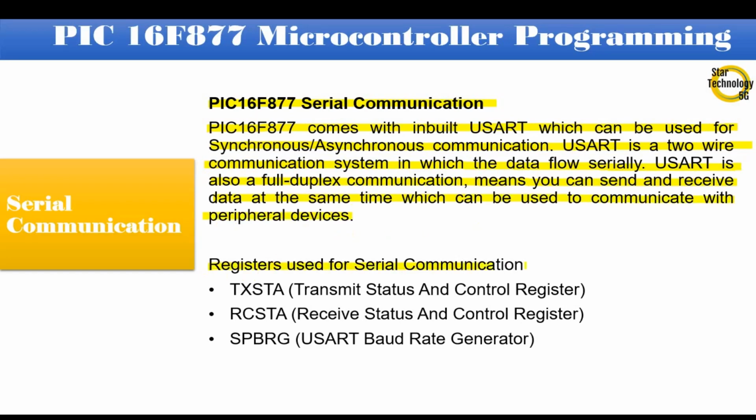Registers used for serial communication. TXSTA, Transmit Status and Control Register. RCSTA, Receive Status and Control Register. SPBRG, USART Baud Rate Generator.